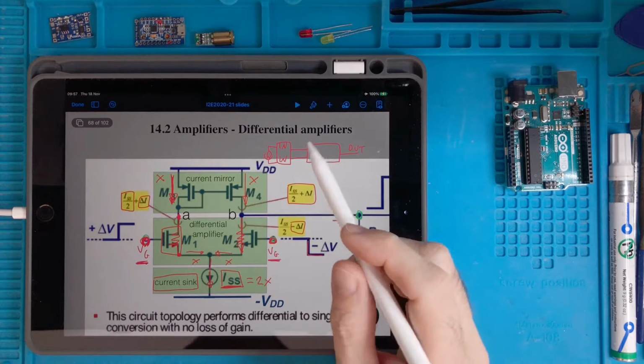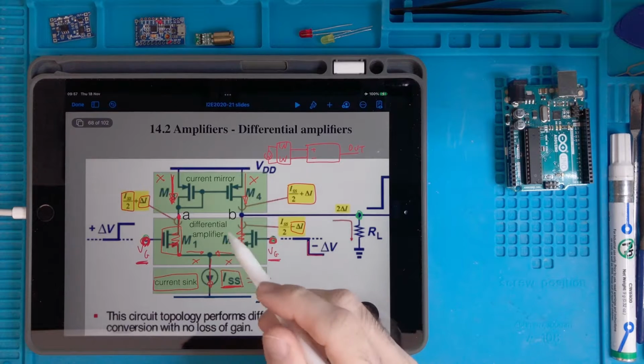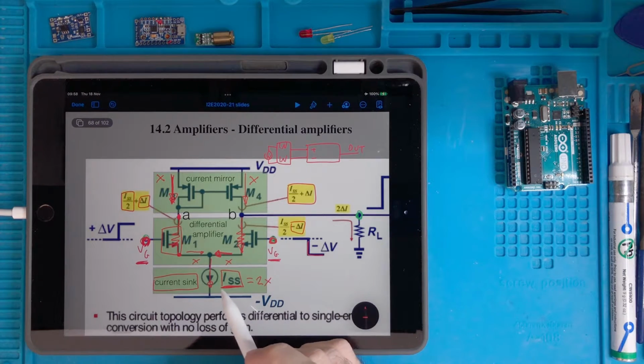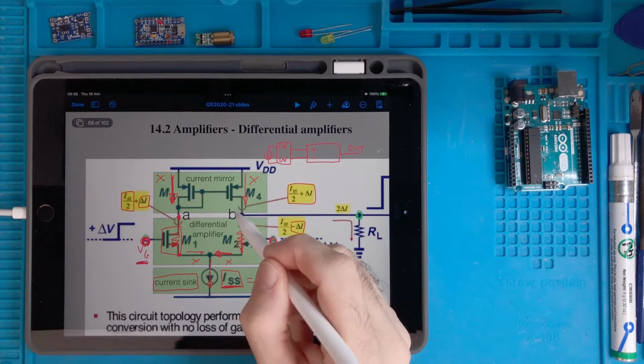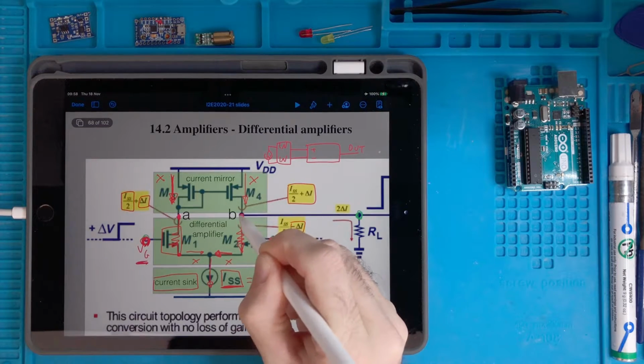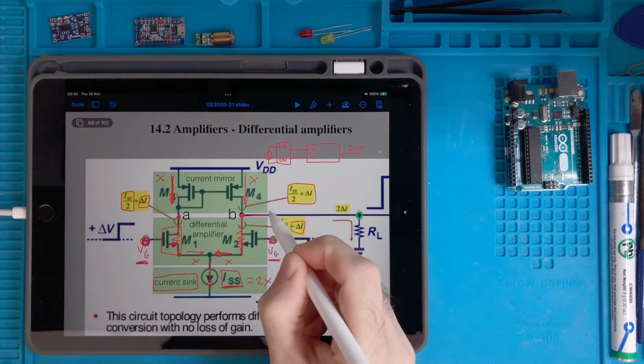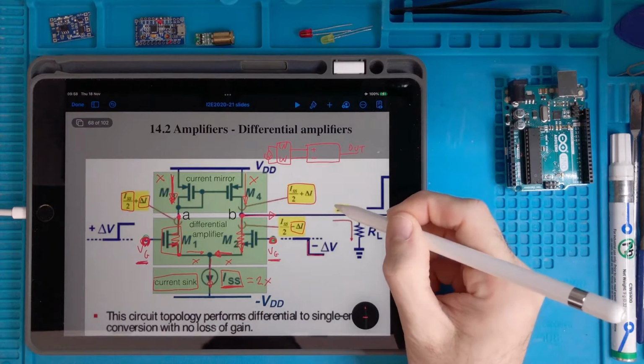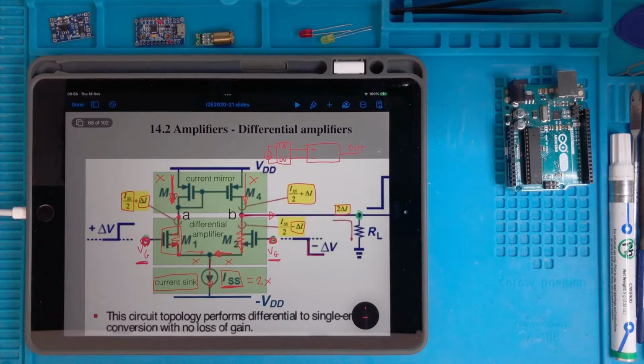And then this thing here still has to be equal to ISS divided by 2, because we calculated this before. So the only possibility to solve this is that out of this node, because of the Kirchhoff principle, a 2 delta I current will exit.